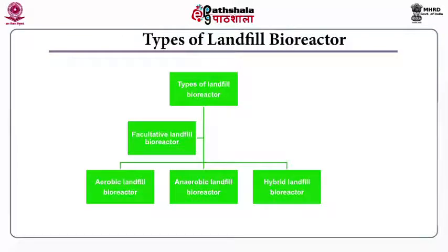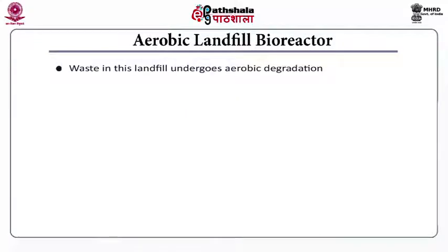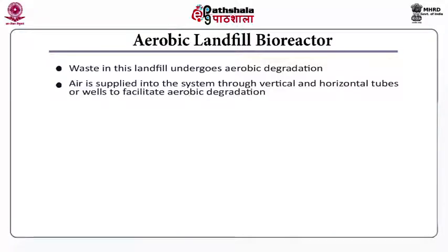Landfill bioreactors are of three types. They are classified based on the working mechanism as aerobic, anaerobic and hybrid landfill bioreactor. In an aerobic landfill bioreactor, waste generally undergoes aerobic degradation. Air is supplied into the system through vertical and horizontal tubes or wells to facilitate aerobic degradation.